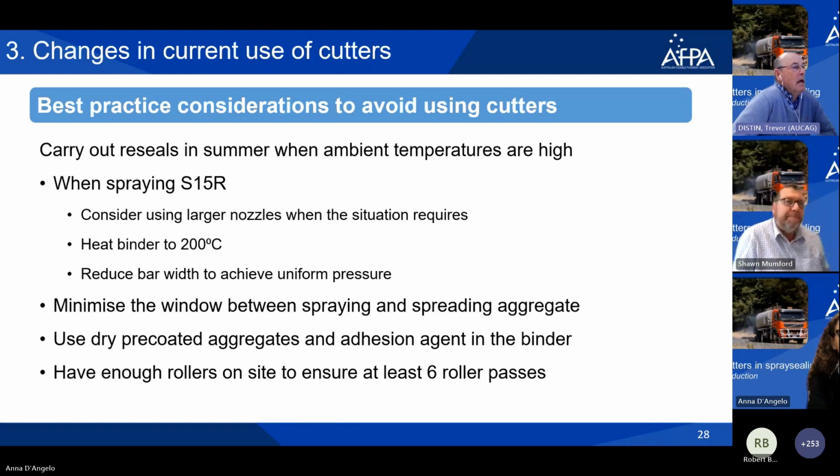And it's not always just in the spraying of the binder. It's also critical that you minimize the time delay from the time the binder hits the cold substrate and the application of the cover aggregate, because that binder viscosity reduces dramatically as it hits that cold substrate, and its propensity to wet the stone is also greatly reduced. So that becomes quite critical in the operation.